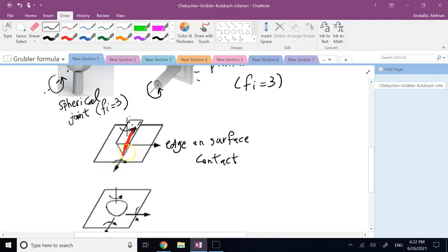You can have this rotation, right? So the object can tilt forward, backward. You cannot have this rotation because if you do, then one side of the edge is going to get off the surface, okay? So this rotation and this translation are out of the possibilities. So you have 4 degrees of freedom left and 2 of them are gone. So Fi for this guy is 2.